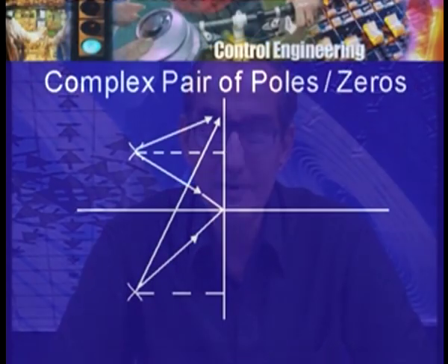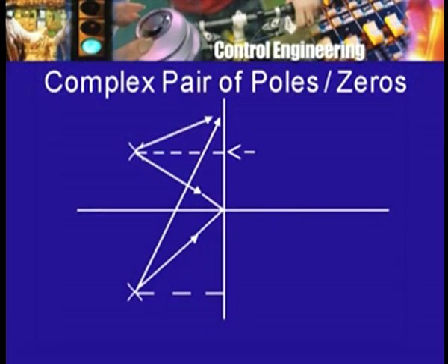What is going to happen in between? In between, of course, the phase shift will go through various values like 10 degrees, 20 degrees, 50, 90, 120 and so on. What will happen at the corner frequency? Suppose I have the corner frequency, this is the corner frequency. Now, what is the corner frequency? Corner frequency corresponds to the distance of the pole from the origin.